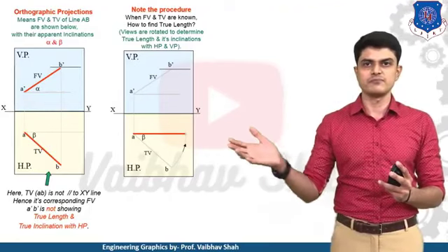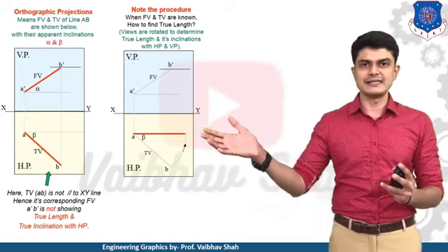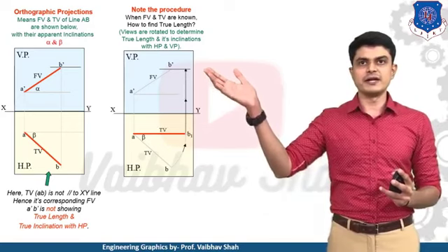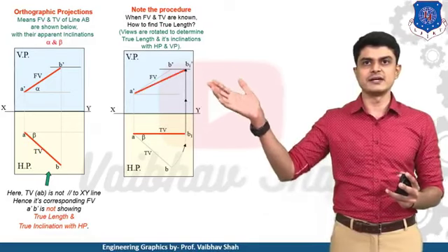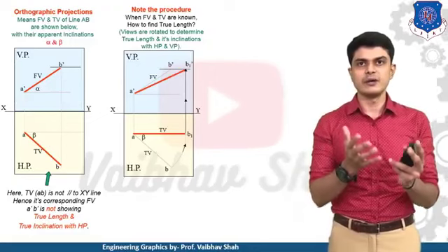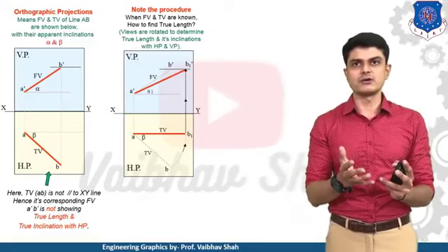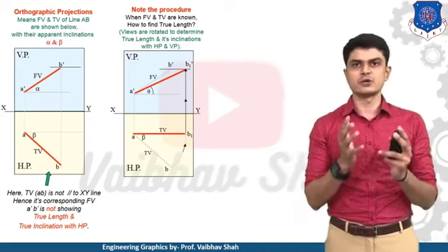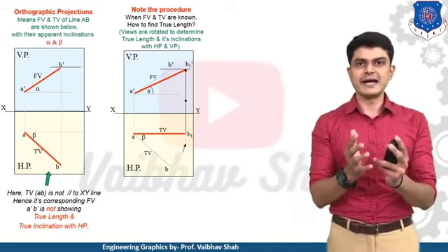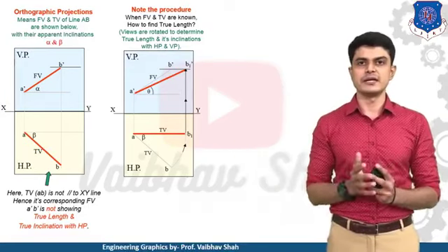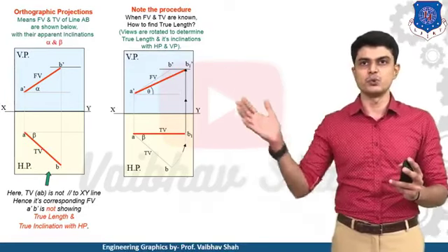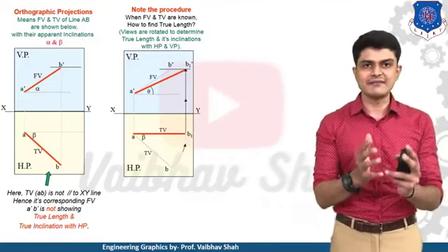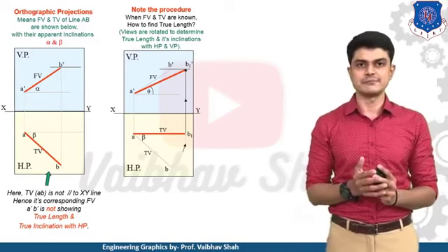So when we convert this top view into a horizontal line, and draw one vertical line from this, and generate one point here, then we will have one line generated here which will give us a true length. So this is nothing but a true length at angle theta. This is how we have generated a true length of a front view by converting this top view horizontal, and we now have this line of true length. After having the true length, we can obviously draw any example.